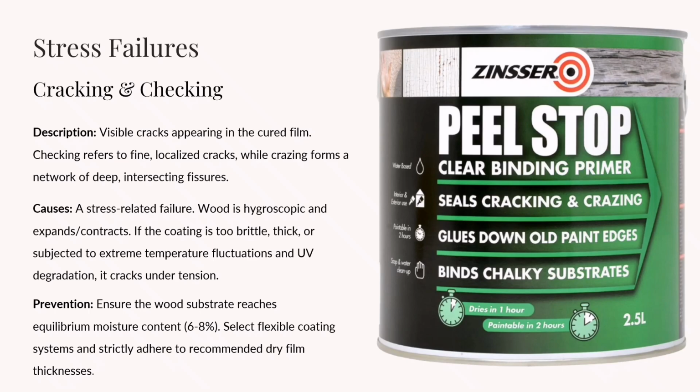To prevent this defect, the wood should have the correct moisture content, usually around 6 to 8%. Using a flexible coating system and maintaining the recommended coating thickness also helps improve durability and reduce cracking.